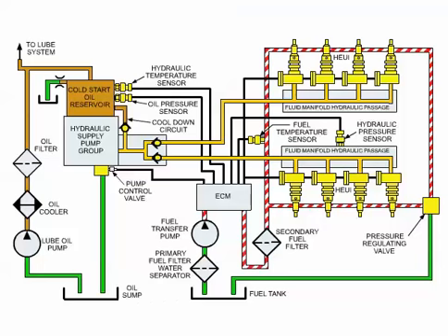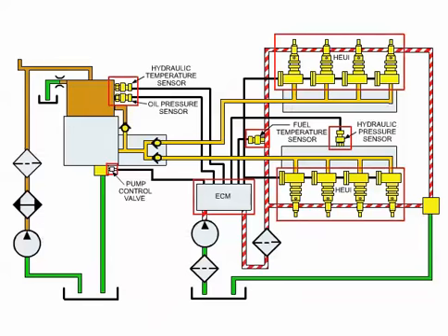This schematic shows the various components in the HEUI fuel system. A detailed explanation of the system and its various components follows later in the presentation. The electronic components in the HEUI fuel system are very similar to those used in other electronic unit injection or HEUI systems. However, in the HEUI system, the injectors are not actuated by a camshaft. Hydraulic actuation is used to drive the injectors.